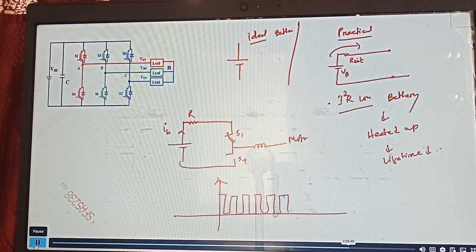It is a pulsed kind of DC because you're doing a lot of switching in the inverter without the capacitor. You see, I did not use any capacitor. So without the capacitor, the current in the battery will be giving a lot of high frequency pulses. If you analyze these pulses through Fourier series, you will see it will have an average value, and it will have high frequency AC components. You can call them harmonics, simple term.